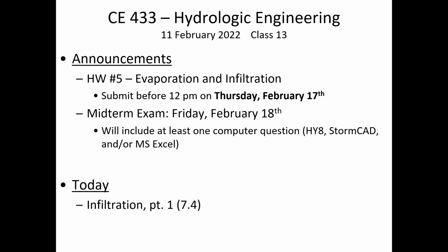Now today we're going to start talking about infiltration, which is a really important phenomenon because it determines how much of the rainfall that hits the ground surface turns into rainfall excess, which is what contributes to runoff. So it's important that we understand the fundamentals of why infiltration occurs and what factors determine the rate of infiltration, but then we'll also look at some methods that have been developed to calculate and quantify the rate of infiltration and the infiltration depths.